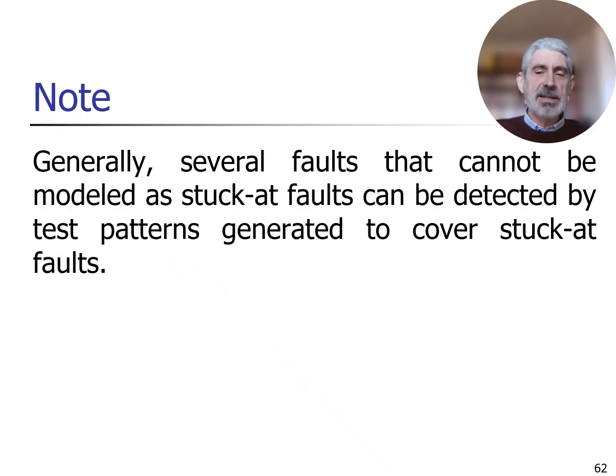However, there is an interesting experimental observation, stating the following. If you use the single stuck-at fault as the starting point and you generate test vectors able to detect all these single stuck-at faults, and then you apply these test vectors to real circuits, you will experience the fact that many defects will be detected.